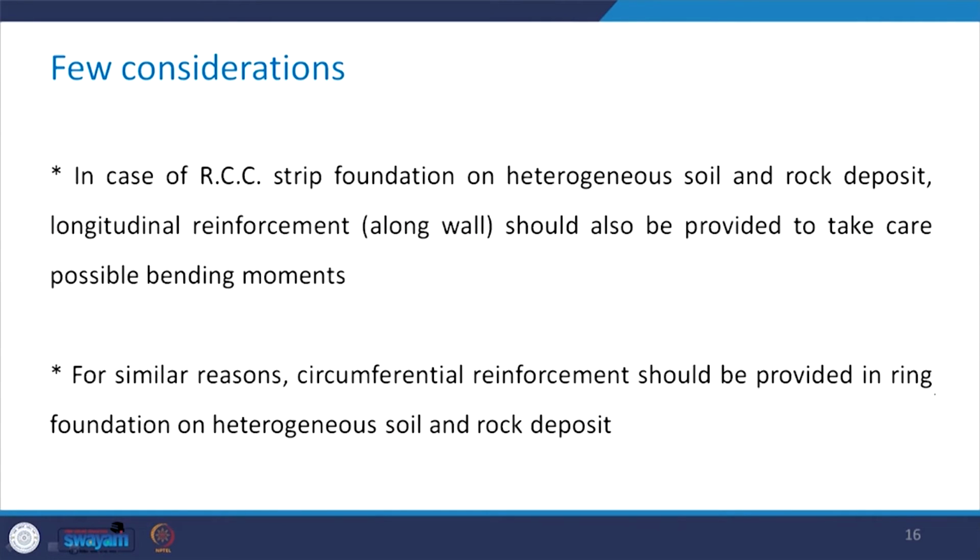In case of the RCC strip foundation on heterogeneous soil and rock deposit, the longitudinal reinforcement, that means along the wall, should also be provided in order to take care of any possible bending moments. Now, for similar reasons, circumferential reinforcement should be provided in ring foundations on heterogeneous soil and rock deposit.